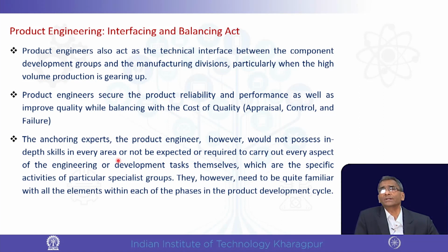Maybe many of you have already studied that, or if you have studied statistics, learning statistical quality control or statistical process control is not difficult at all, because with minimal knowledge of statistics also one can grasp that idea. Basically, the idea is that the process should behave steadily, and it should lie within the desirable control limits, and not cross or touch the specification limits. That is the tolerancing that I was talking about. The upper limit and lower limit should not be touched.